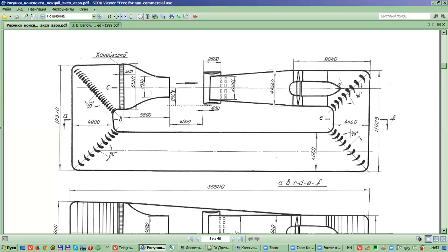After this part, they call it the nozzle in a tunnel with an open test section, and this is also the inlet. And after the inlet, you have an opening in the contour, the slot, and this slot is designed for the additional pulsation in airflow; the slot dampens this pulsation and improves quality of flow.